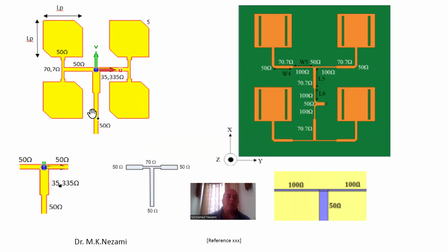So let's start out with just a simple 2x2 antenna network where the antenna port is 50 ohm, basically. You can see that in here we have used, and these are the transformers, basically, like I said before, either this one here, which has two 50 ohm lines in parallel with the quarter wave line that matches the 25 ohm to 50. This one matches the 50 to 100, okay? And this one here is basically two 100 ohm lines in parallel, which is 50 ohm, so there is no need for a quarter wave line here to do the matching.